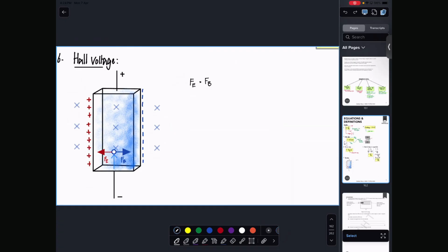Right. So let's say you have a Hall probe right now, and you place it next to a magnetic field, and it tells you it's 4 volts. How much is the strength? Could be anything, right? I don't know what 4 volts means. However, I take that Hall probe and I place it next to a magnet that I'm aware of. That is 1 Tesla, and 1 Tesla gave me 1 volt. Now 4 volt means what?